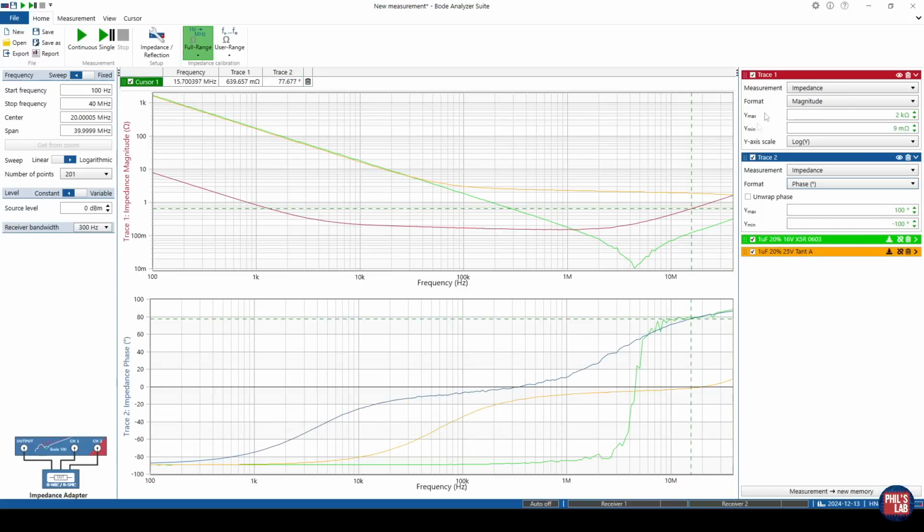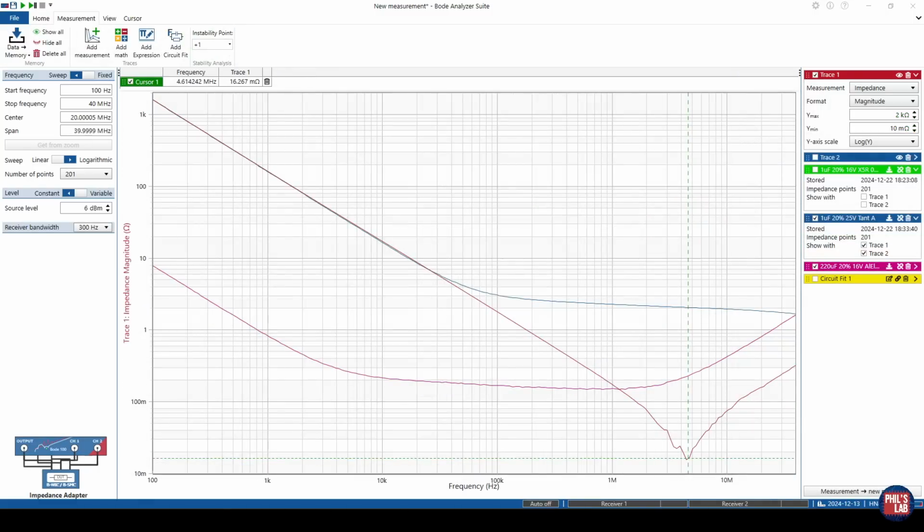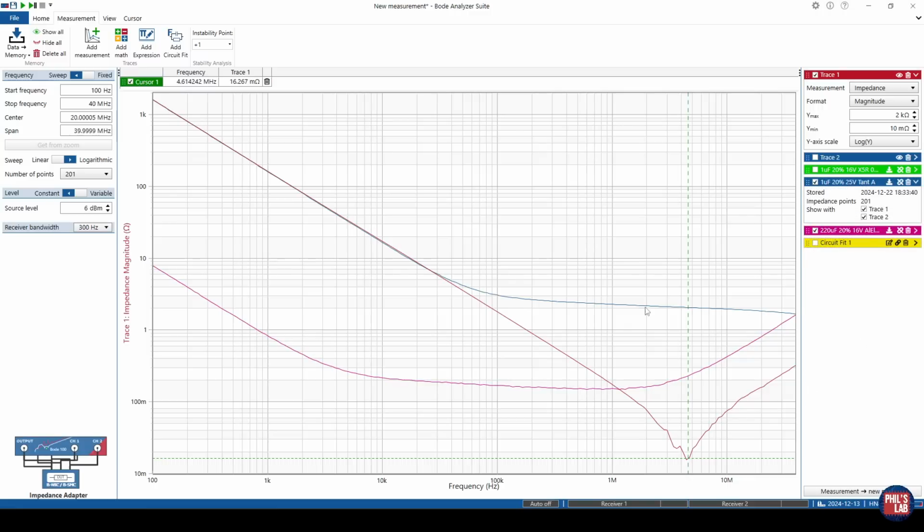So I personally think this tool is super cool. We can actually do real-world measurements of capacitors, see what their frequency ranges are, what the ESR is, the ESL, compare different capacitors and see if they're suitable for our specific application. Just comparing these three different capacitor types very briefly, the multilayer ceramic, the tantalum, and the aluminium electrolytic, these have very, very different characteristics. This is due to their dielectric type, their package size itself, the lead spacing, physical size, and more.